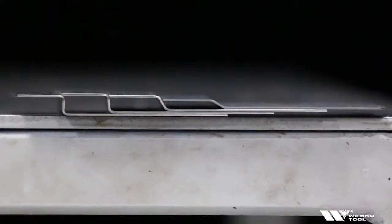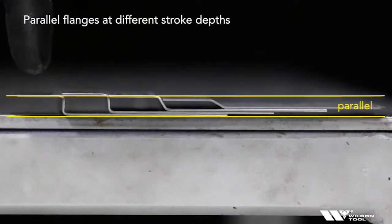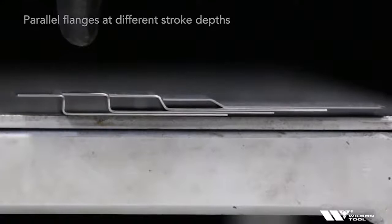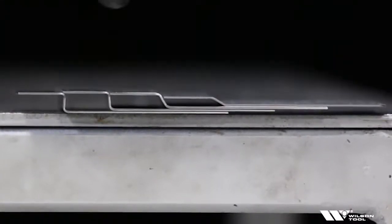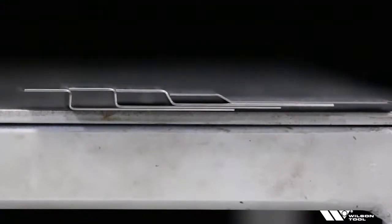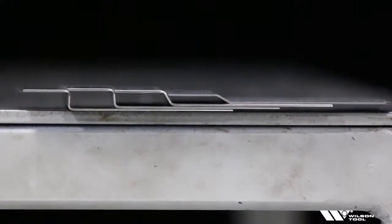So now let's take a look at the bends that we just made on the press brake. And you can see there's the offset that was overbent. We actually applied extra tonnage to get it to spring in. Here's the bend that went to the included angle, 90 degrees. And here are the bends where we just backed the stroke off, and you can see as we back the stroke off, the angle changes, and so does the height of the offset. So we could control that stroke to get our height, live with the angle, and we just saved a lot of time and money making tools in our tool room.